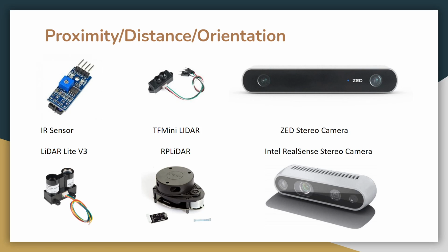and wavelength. It's a very similar analogy to the ultrasonic sensor, where they have an emitter and a receiver, and an emitter and a receiver over here as well, and even the IR sensor has an emitter and a receiver. So all of these sensors emit infrared and then receive the infrared, and they use the same analogy as ultrasonic sensors to find the distance between the sensor and an obstacle in front of them. So yeah, this is the TF mini lidar.